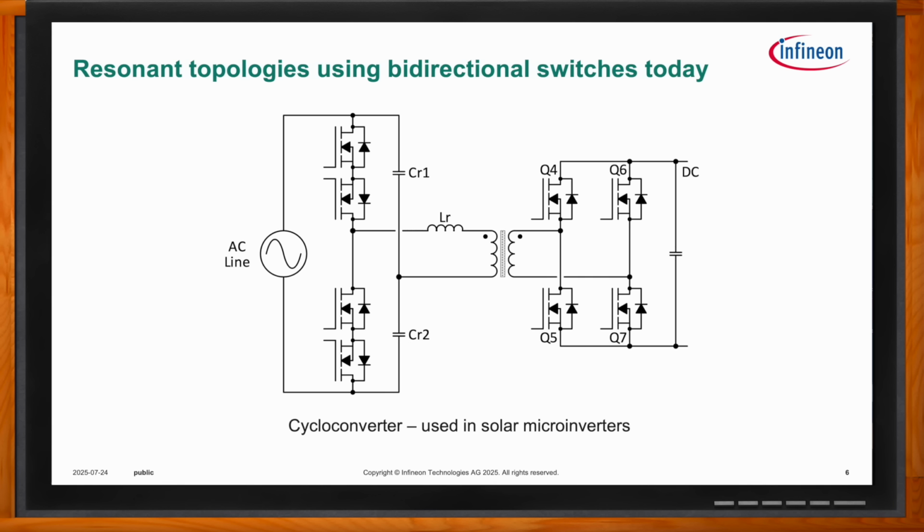So, Eric, this looks really simple, but how can this work with no DC bus in the middle to reduce ripple and store energy for line cycle dropouts? There's always a compromise with any approach you take. The advantage of this topology is it's simple, it's very efficient because it's resonant, so you don't have switching loss. However, yeah, there's no DC link.